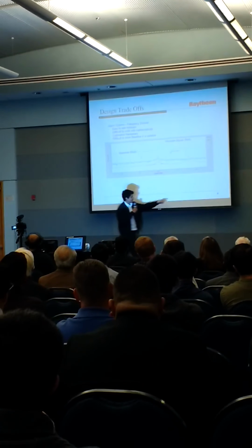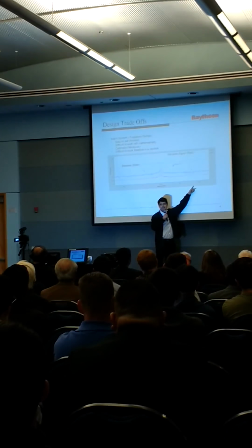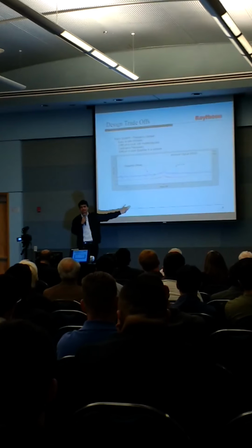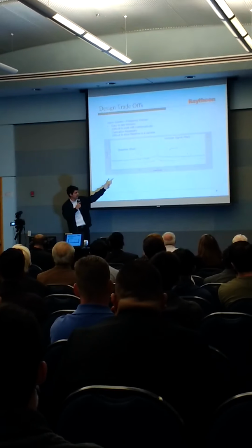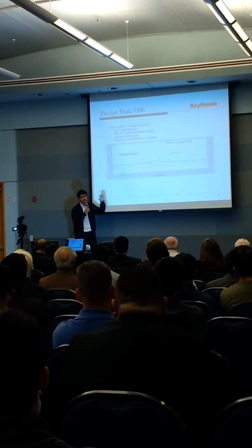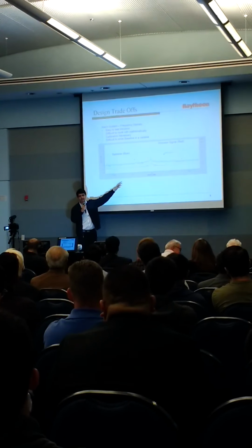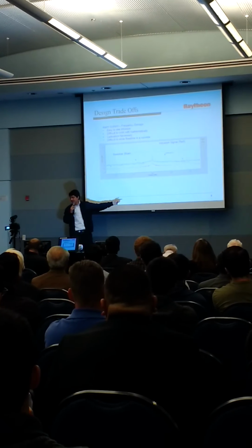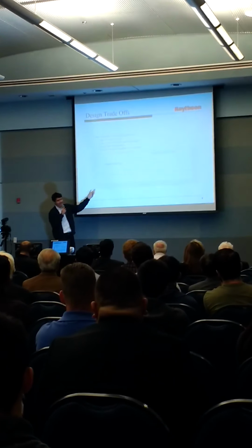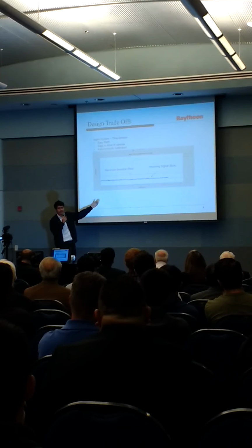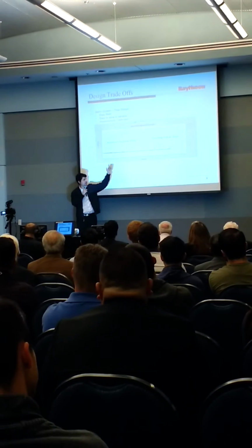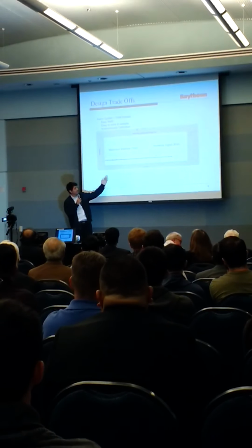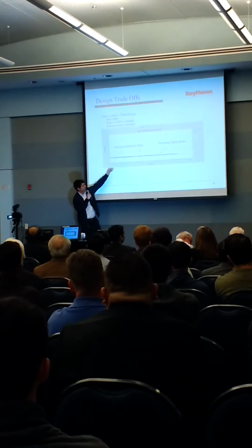So I'm going to get in here. It looks easy to see the intrusion, but it's hard for the computer to detect that intrusion. For us, it looks simple, but for the computer, it's hard, because the signals are messy, they're hard to store in a variable. So we move it to time domain. And in time domain, these signals are cleaner. Like our baseline that we had captured is a constant. And constants are easy to store in variables. And it's easier for the computer to know when there's an intrusion.